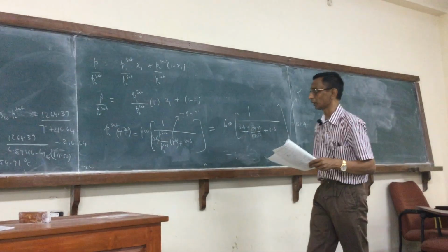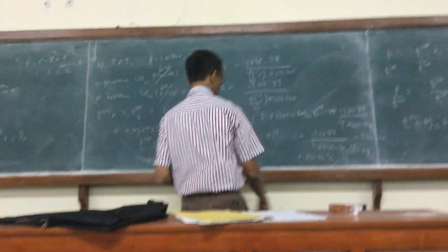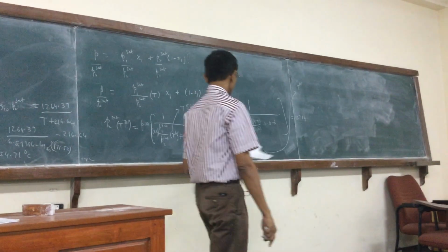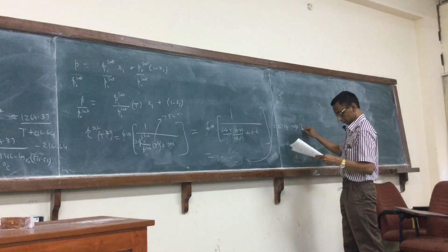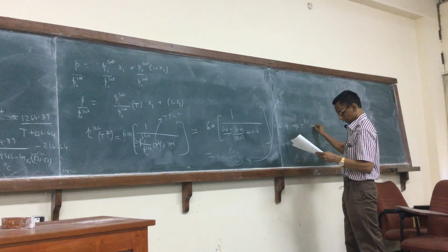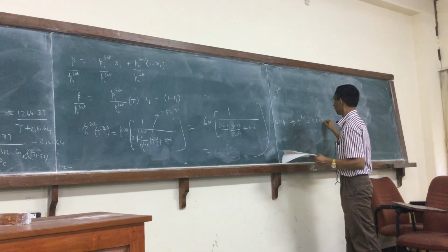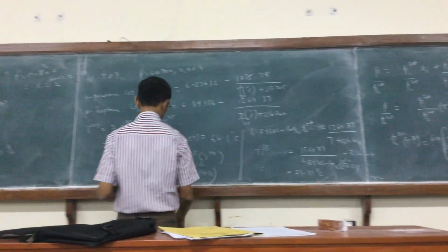You can see all the way from 264.25 it comes down to 170 because it's progressively decreasing. 171 and I come to 157.14 T2 sat, which would imply that T2 is actually equal to 52.51. We have to see that there is clearly a progressive convergence.